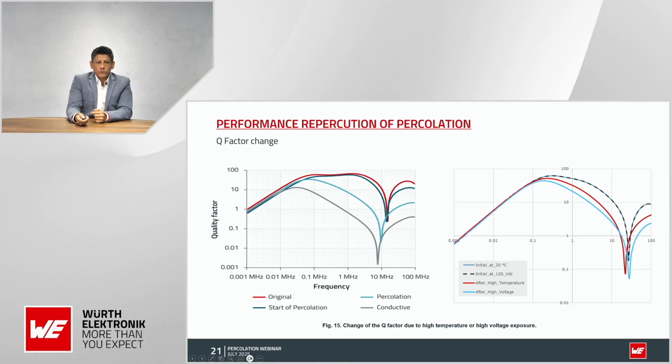On the other hand, what was interesting is that when we used the same competitor part and compared high voltage and high temperature, we found that the curves change in both scenarios. So we have one part exposed to 120 volts. We apply a round of shots to 120 volts. We put it in real applications, and due to our voltage specification, we guarantee that the part performs well. But I increased the voltage a little with some peaks of 190 volts, and then with some peaks, the curve changed, as we can see here in the light blue color.